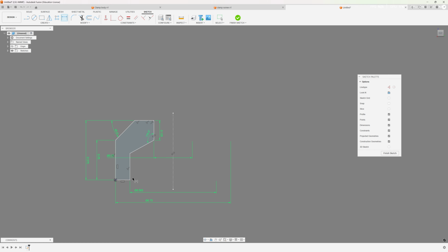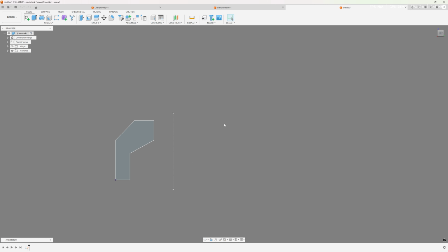All right, so by selecting the line type of a center line, instead of dividing by 2 like I did on the pin previously, it allows me to skip that divide by 2 function. It's really good when I have something like this where I have a half clamshell kind of thing, and I can then put the line and then put a full diameter. And once I get my sketch fully finished, I can hit the Finish Sketch button.